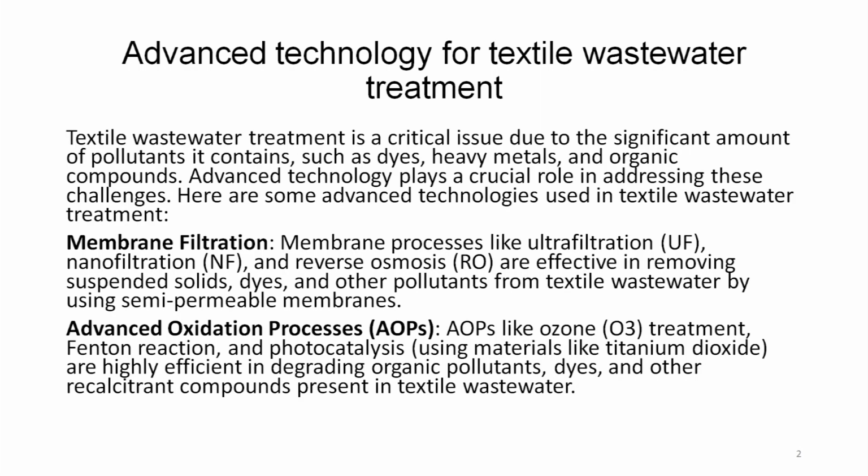Membrane filtration. Membrane processes like ultrafiltration UF, nanofiltration NF and reverse osmosis RO are effective in removing suspended solids, dyes and other pollutants from textile wastewater by using semi-permeable membranes, and these membranes are of different porosity.